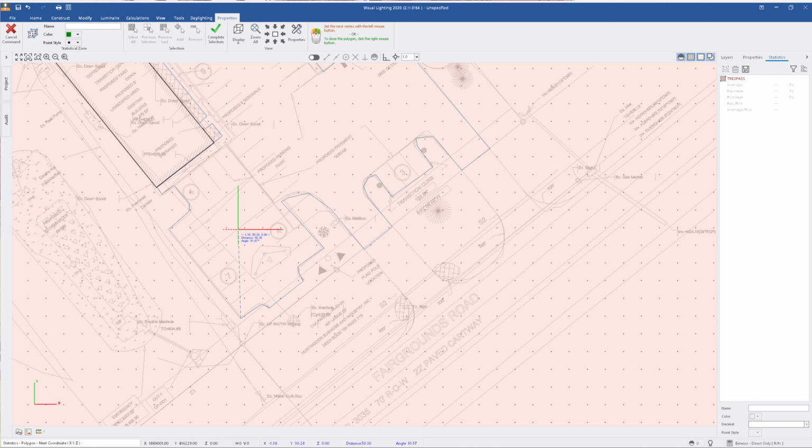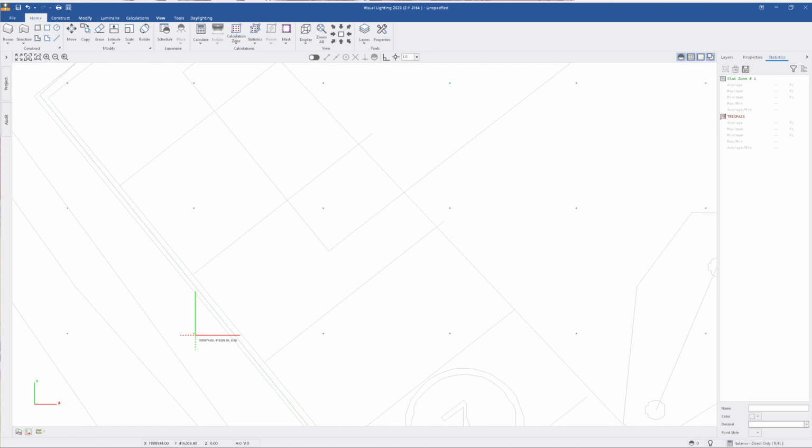Now if I zoom in, you'll notice that outside of the zone, these are really small, they are just a plus symbol. Inside the zone, they're asterisks. So over here, I can click on that stat zone, go down to the bottom, and I'm going to call this paved area and return. And the paved area all has green as its little point styles. You can change the point styles, there's lots of different ways. I usually just leave them the way they are.